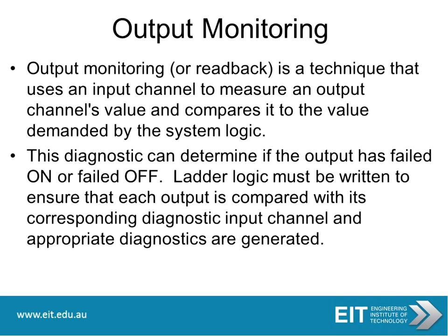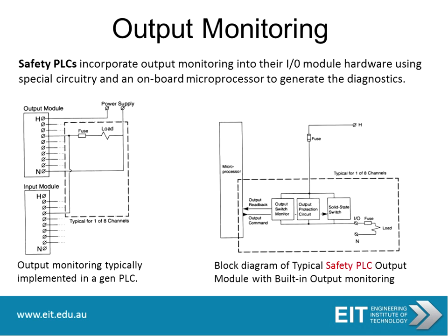Output monitoring, or readback, is a technique that uses an input channel to measure an output channel's value and compare it to the value demanded by the system logic. And this diagnostic can determine if the output has failed on or failed off. So your ladder logic must be written to ensure that each output is compared with its corresponding diagnostic input channel, and appropriate diagnostics are then generated.